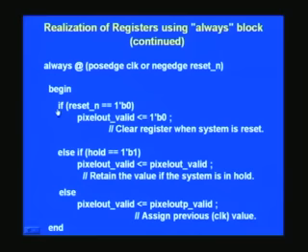So you are saying the hardware is clear, but the program also works sequentially? The assignment statements, pixel out valid, yes. Next statement, pixel out valid is pixel out pre-valid. Yes, that means this will happen only after this is done. Yes, it is precisely the same, because the hardware delay is happening. That is because the core of the statement is right here. You notice that the previous value is only assigned here at the present clock, so unless the previous value changes, it will happen only after the clock, a delay of a clock. That could have been explained there itself, because everybody knows this. Fine.